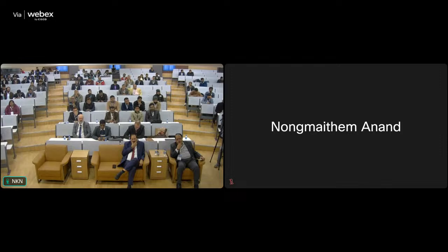Now you see the variation in each parameter, right? It's mentioned here. And you will see in the good rock, the variation is less. The minor change in JR, JA, no change in JW, because joints are tight there. So it is not affected that grout will percolate, because as the rock quality is improving, the joint conditions and other things are improving. So the grout will not percolate much. Therefore, the effect of grouting is expected less. So expected effect on Q is shown qualitatively.